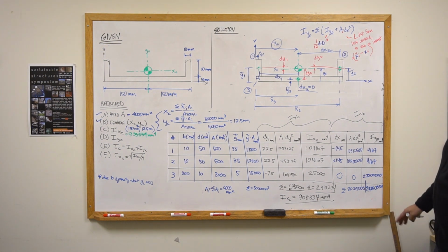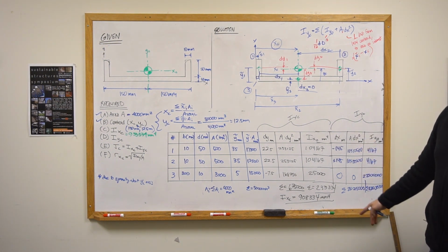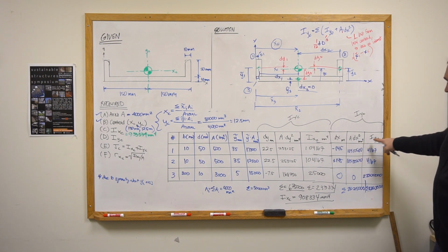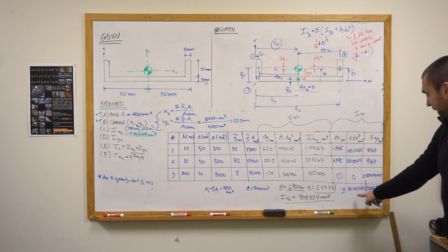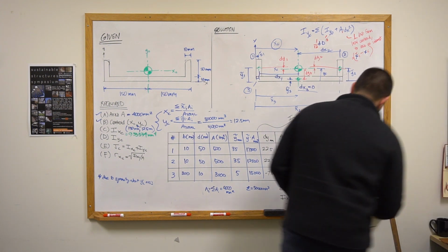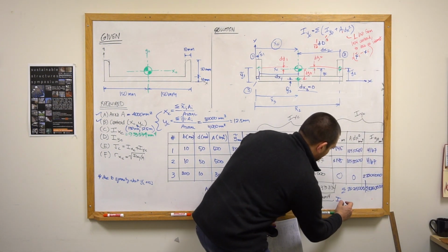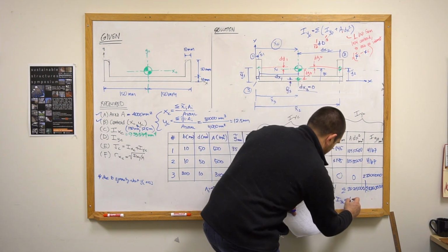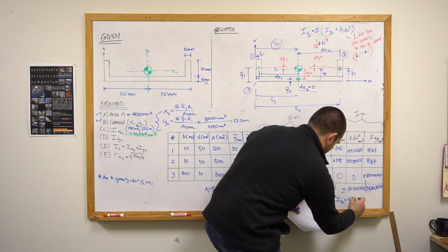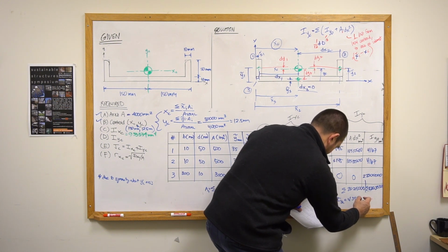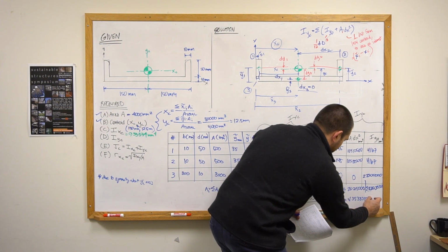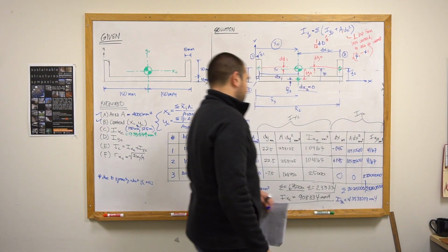And all we need to do to calculate the total moment of inertia, which is due to both the parallel axis term and the moments of inertia about the local centroids, if I add up these two values together, I get that I_yc equals 43,533,333 millimeters to the fourth.